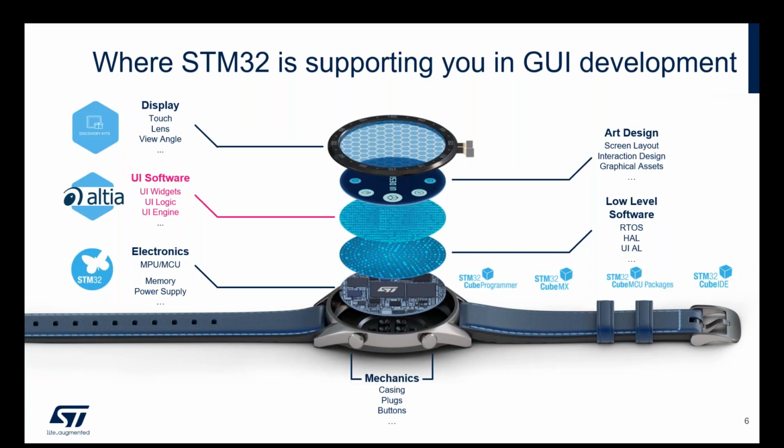So we do have an exploded watch here, but it could be a thermostat or anything else, of course. And what we do at ST, we of course have the silicon itself, an STM32 MCU or MPU. Together with this, we supply Cube Programmer, CubeMX, drivers, HAL layers, and so on, and the Cube IDE as free tools. I'll not dive in too much into this, but it helps you to configure your microcontroller or microprocessor, to write your code, to generate a project, and so forth.